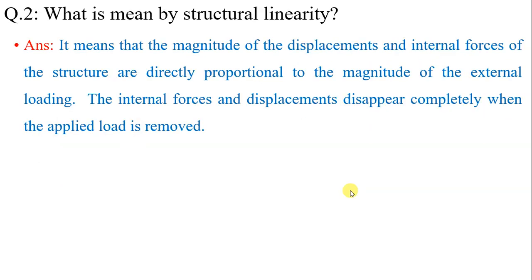Question number 2. What is meant by structural linearity? Structural linearity means that the magnitude of the displacements and internal forces of the structure are directly proportional to the magnitude of the external loading, and the internal forces and the displacements disappear completely when the applied load is removed.